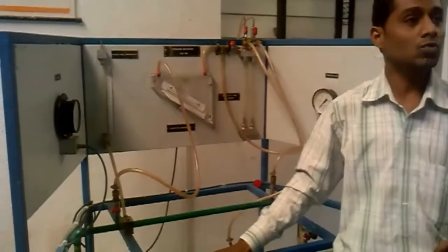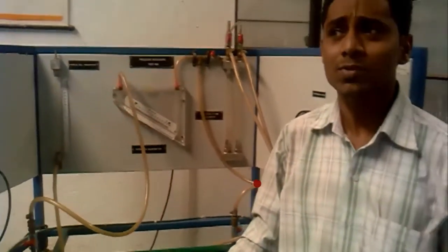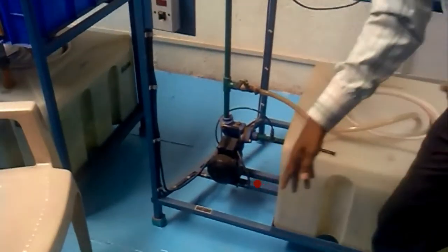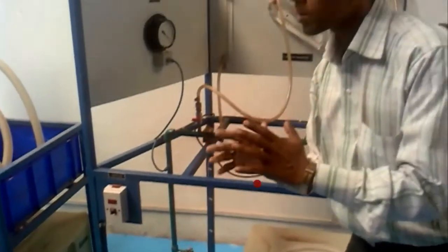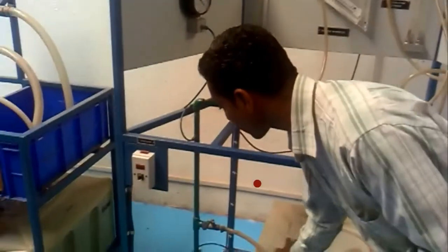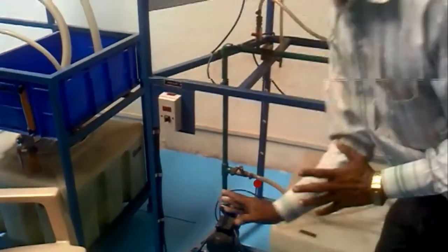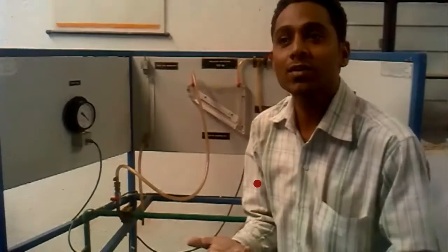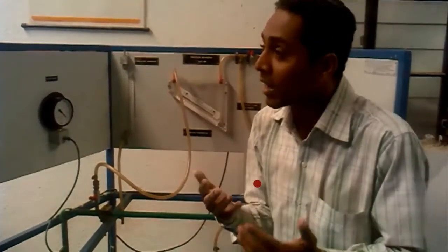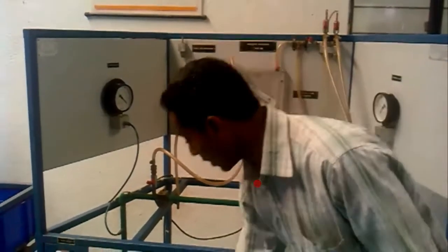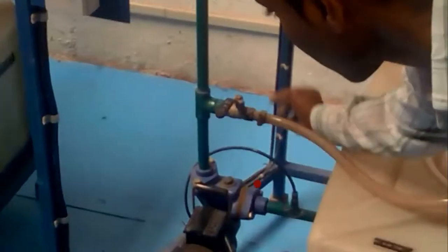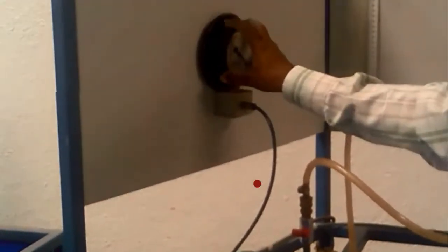And negative pressure means what? Pressure below atmosphere. And where is this pressure? That pressure is in the suction line. Because there is pressure below atmospheric, water from the tank comes into the impeller. The impeller sucks the water, meaning pressure below atmospheric pressure is created there. So how can this pressure be read? Here in the suction line we have taken a connection, and we have given it to this vacuum gauge.